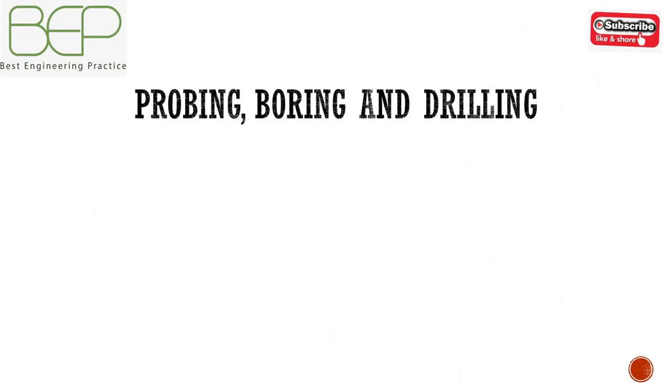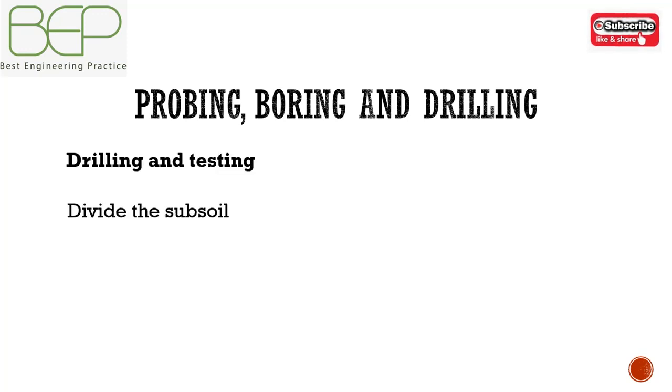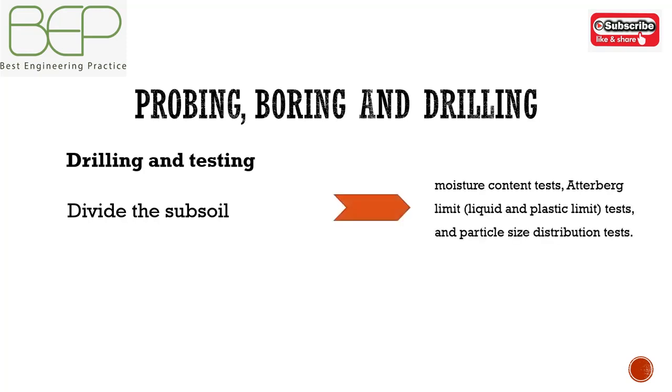The objectives of site investigation, drilling and testing are threefold. The first is to divide the subsoil into simplified soil types or groups. Soil grouping and the assessment of the soil variability within each group is normally carried out on the basis of visual sample description, moisture content, Atterberg limits tests, and particle size distribution. These last three types of tests are often referred to as classification tests because they are used to classify the soil into groups of materials which are expected to have similar behavior.